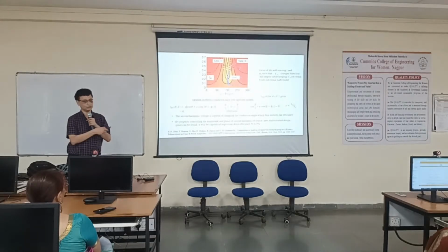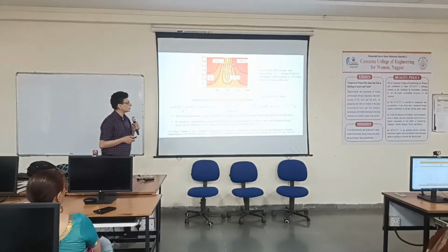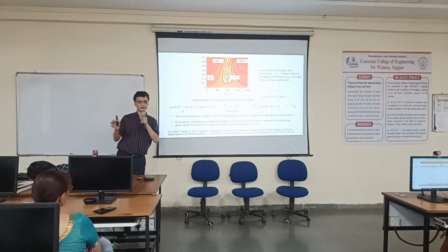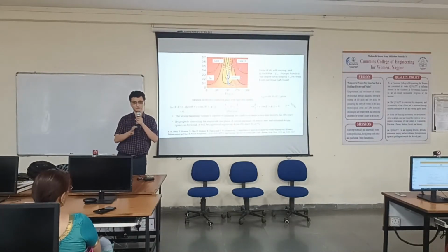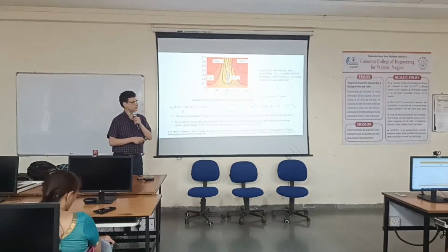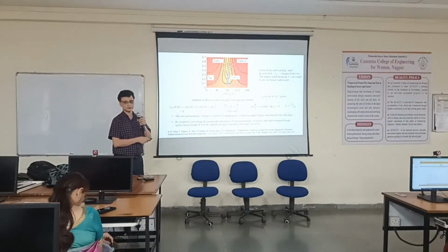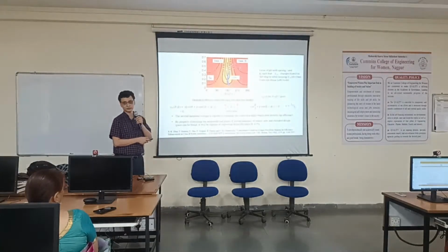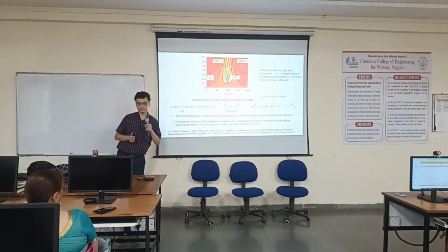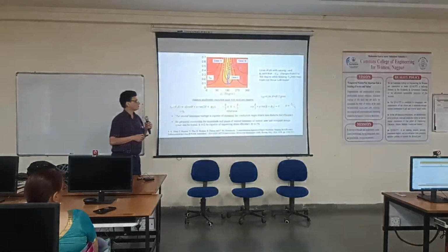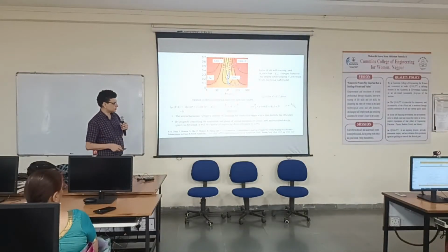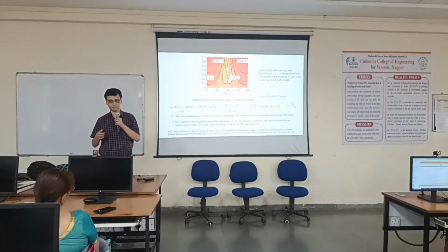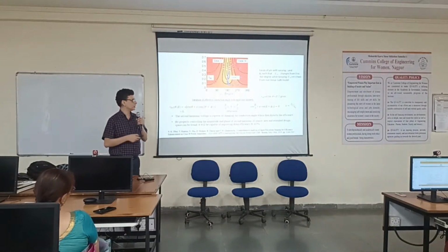So it takes some time to achieve this. It means, suppose you have 3 amplifiers or an infinite number of amplifiers which have the same conduction angle but different nonlinear parameters, then what would be the values of those nonlinear parameters? This equation. Okay, that's how this is made. So this one was published in 2019, and we did our modeling for that load, the optimum load, based on this load.